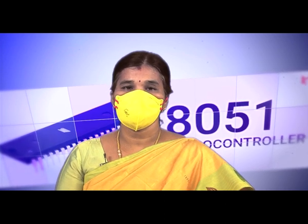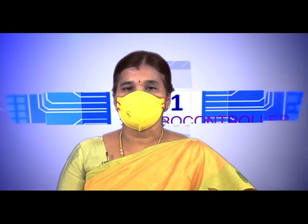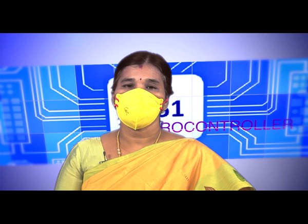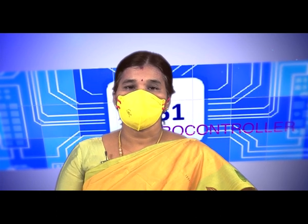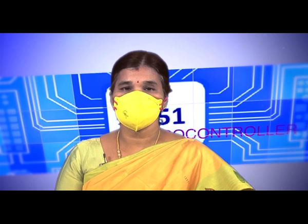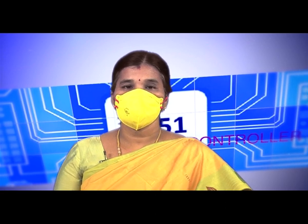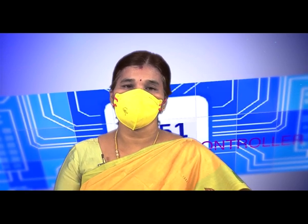In today's session we have discussed the 8051 microcontroller. This controller is the basis for embedded systems. It is an 8 bit microcontroller, which means it has 8 bit data lines. It has two 8 bit registers and 32 registers internally in the register banks, along with two 16 bit registers, and especially it has special function registers which support peripheral communication. So, before starting any design with the 8051, we have to know these internal structures along with the internal registers, and only then can we start the design easily.